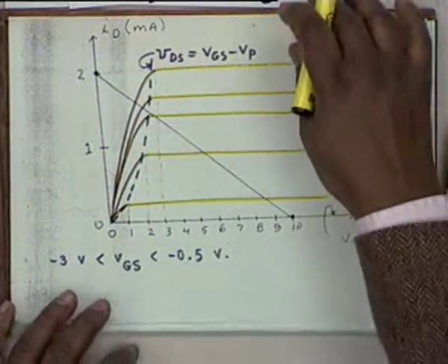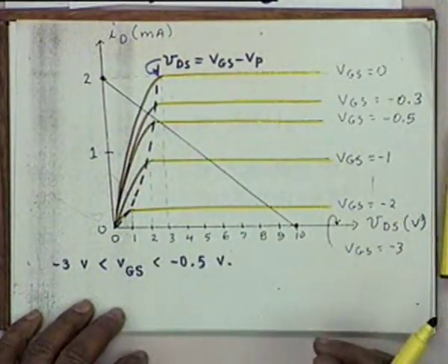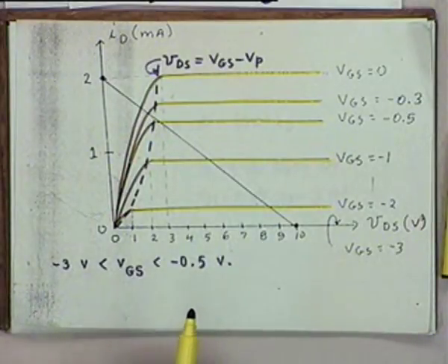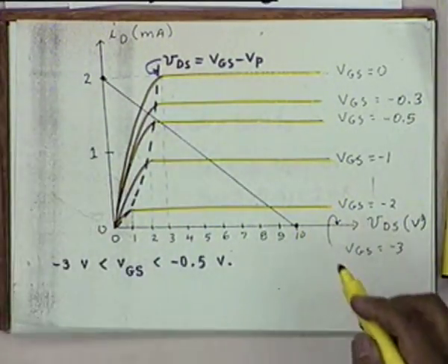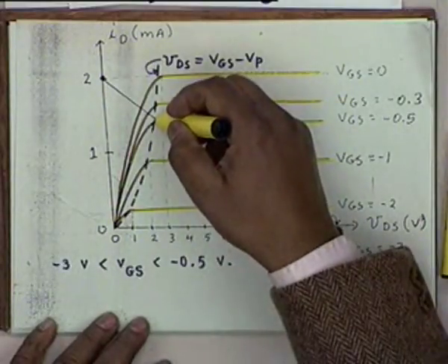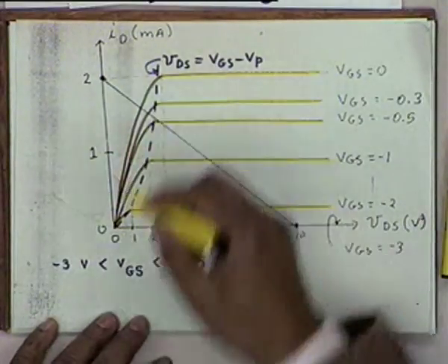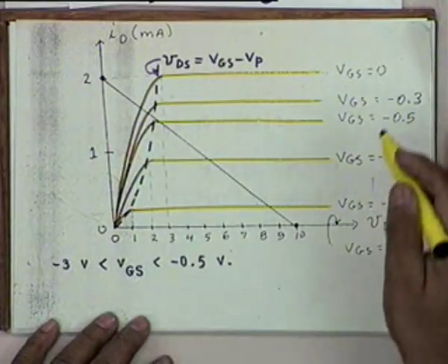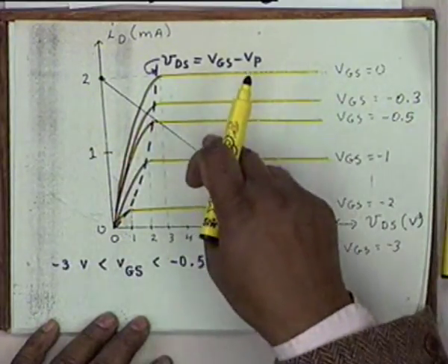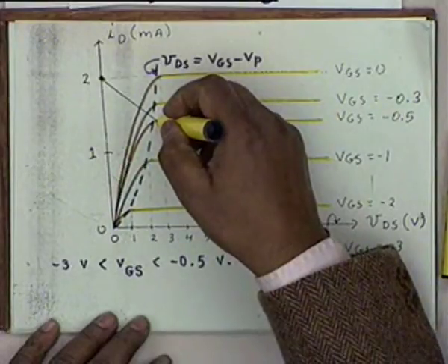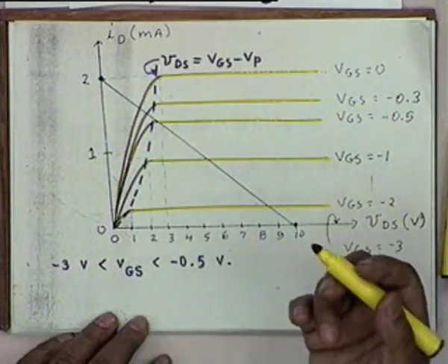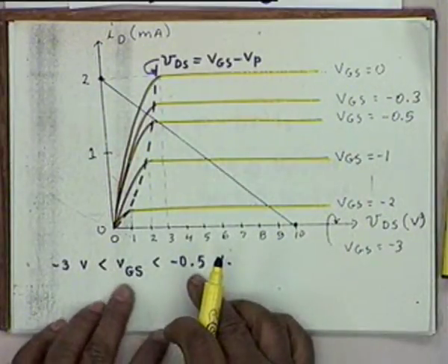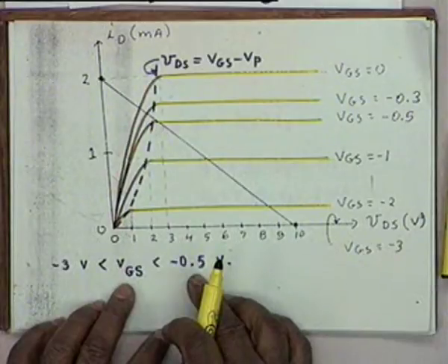And you also see the last part of the question, what values of Vin are required to obtain operation in the saturation region. You see, the operation must be on this load line. So on this load line, you should not go into the ohmic region, you should remain in the saturation region. This is why I drew that VGS equal to -0.5. This is approximately -0.5, and therefore VGS must be less than -0.5.